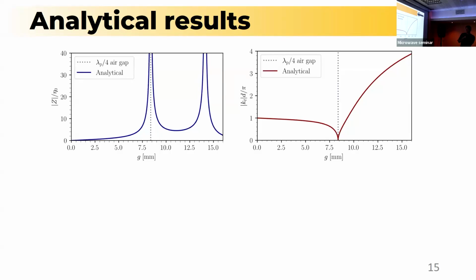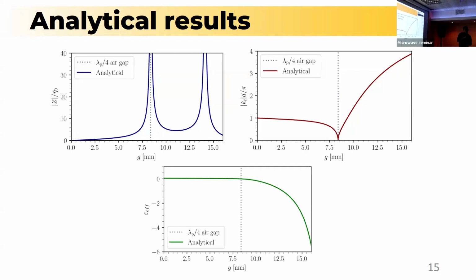So it was inside of the cosine function. So when we have 0, this cosine function will be the maximum possible and will be uniform along the transversal section of our wire media region. And if we check the effective epsilon, we can see that at the lambda over 4 condition, this epsilon becomes 0. Particularly here, we have that condition of the epsilon equal to 0.